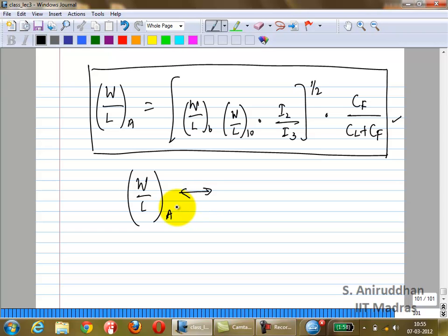And if the resistance changes in one way with temperature, for example, it has a certain temperature coefficient, the other resistance is also going to vary the same way. Right? With process, it's going to vary the same way. So you have to use the same type of resistance. Okay? So we'll look at that in next class. Okay?